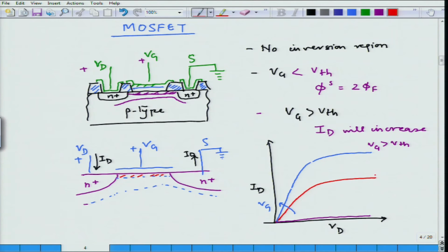So, what is happening at higher Vd? At a particular given Vg, if I am applying the drain voltage for this value, it works as a resistor, but at one particular point what we see is that the drain voltage here becomes equal to Vg minus V threshold. At this particular point, the voltage dropped between the gate and the channel is 0. As a result, this particular channel is pinched off. If I plot only this particular portion, the channel at this value is going to look like this, the channel is getting pinched off right at the edge of the drain, and as a result now there is an increase in resistance and the current gets reduced after this pinch off point, and then eventually it saturates out.